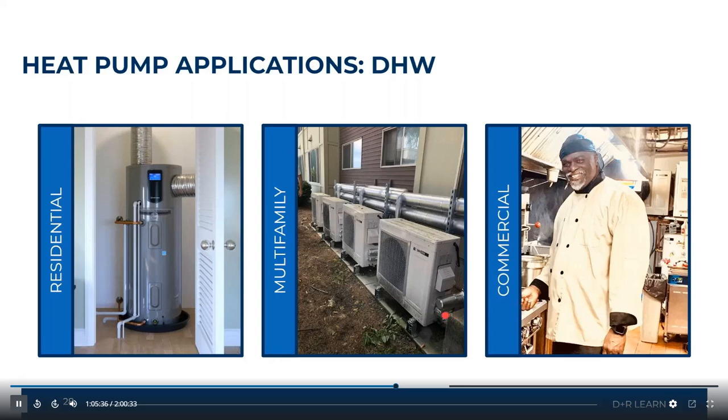You probably don't want it that hot, but you do know you have the capabilities to provide that with a heat pump system. And the refrigerant being used is CO2, which is a newer type of refrigerant being used in these heat pump systems. And this specific refrigerant is very ozone friendly.